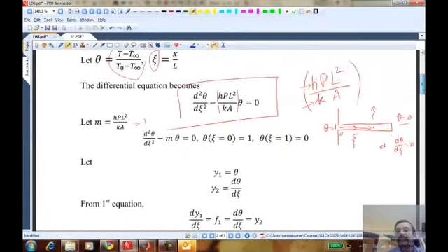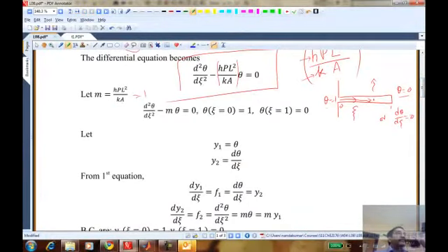So if you go back to this picture, there are two mechanisms we talked about. K increases the rate at which heat is transferred this way, and H increases the heat transfer to the surrounding. In reality, on a CPU, for example, you have a fan, and you increase the speed of the fan. That means you are removing more heat through this mechanism. So you are increasing H in a sense.